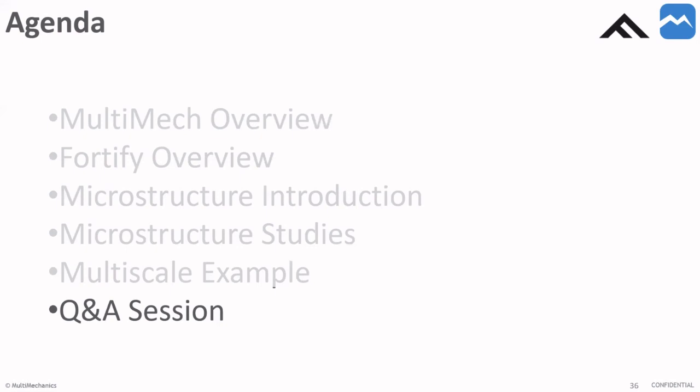There's only one node in between the interfaces. Once you reach a certain traction strength that allows for debonding, a node will automatically be inserted and the crack will automatically be inserted. That's another benefit, is that these cohesive zones can be really tricky to insert by hand, so we do it all automatically.